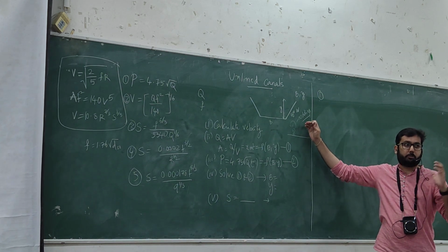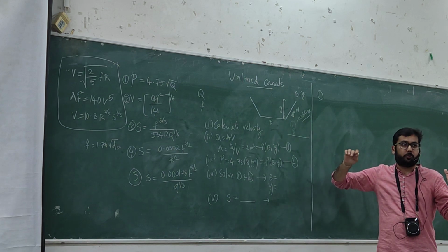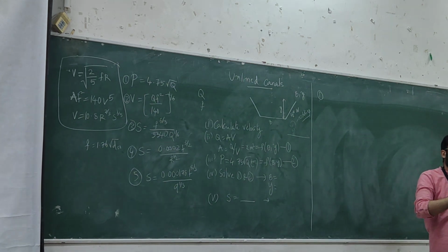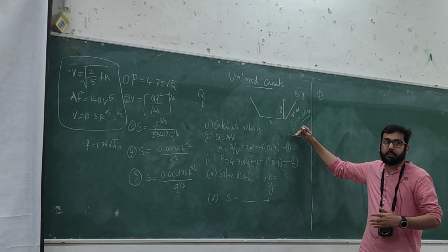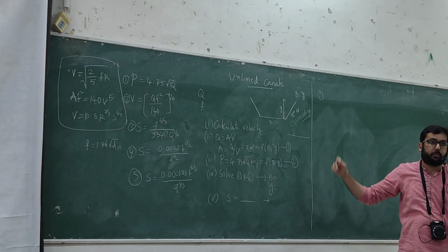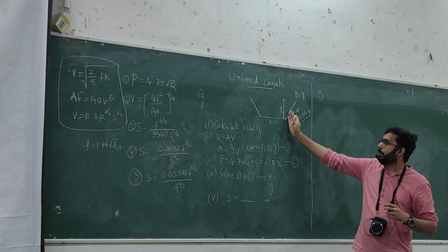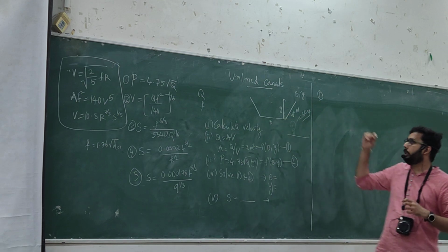So we are talking about suspension and then some turbulence that is mixing the flow. So if there is mixing in the flow, then the sediments would be in suspension, so they would not get a chance to get deposited. So that is why in both the theories we are considering eddies as the main phenomena for keeping the sediments in suspension. Whereas in Lacey he considers eddies from the side slopes as well. In Kennedy he only considers turbulence from the bottom.